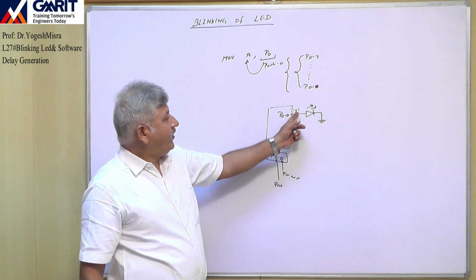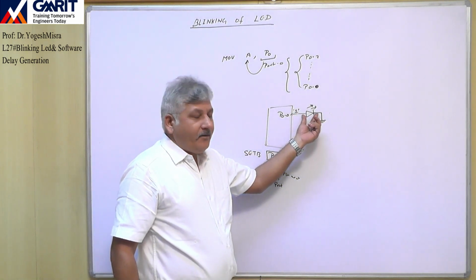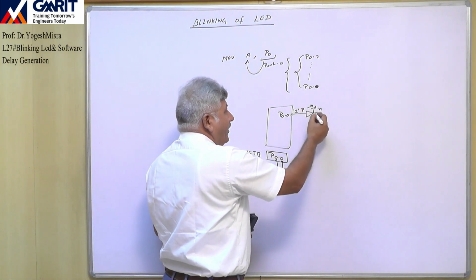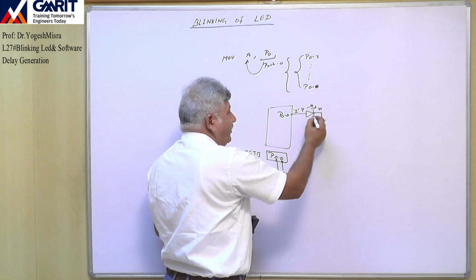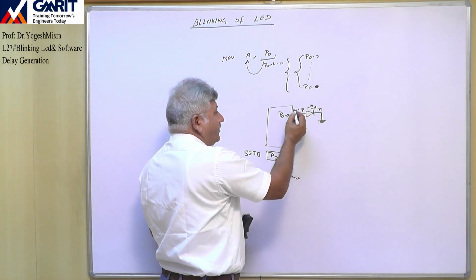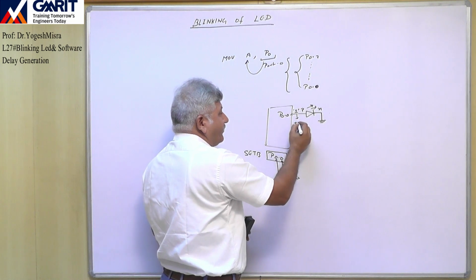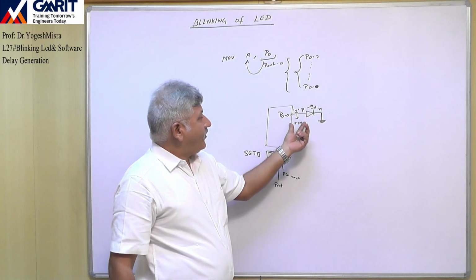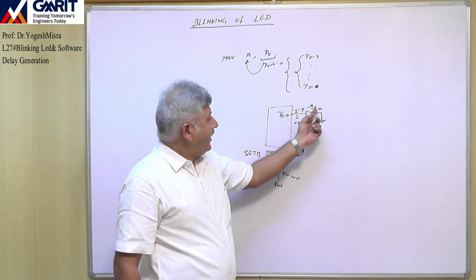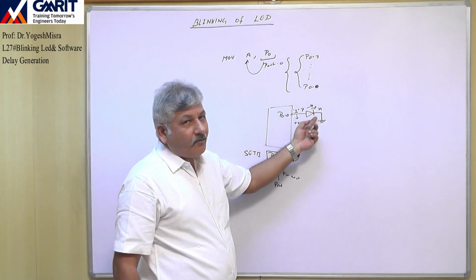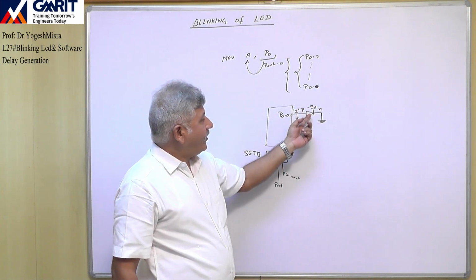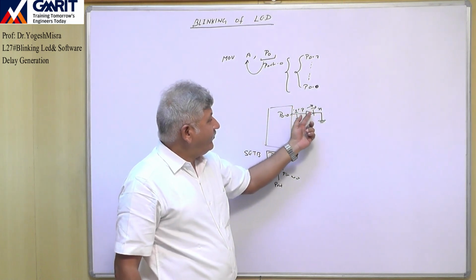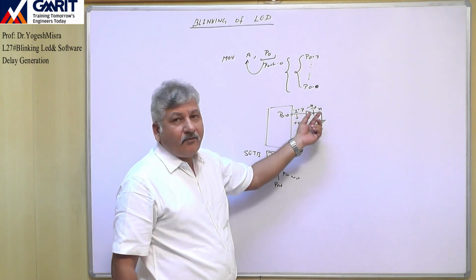So now this pin is 1, and this is an LED. In this LED this is the N terminal, this is the P terminal, and the N terminal is connected to ground. Now at the P terminal we have generated 1. 1 indicates VCC, that is plus 5 volt. So now the P terminal is connected to plus 5 volt and N is connected to ground. So now this LED or diode is forward biased. If the diode is forward biased, then current will flow through the diode. And since it is an LED, when current starts flowing through the diode, this LED will glow.